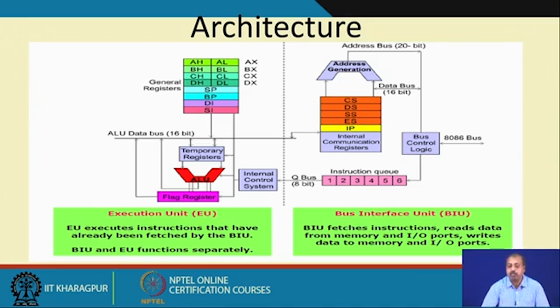As you know, in case of 8086 we do not have two separate buses. So, it is multiplexed, AD0 to AD15, and we have also got the status lines multiplexed with the bus. So, ultimately it is a 20-bit bus that is going out of 8086. So, this is the 20-bit bus.